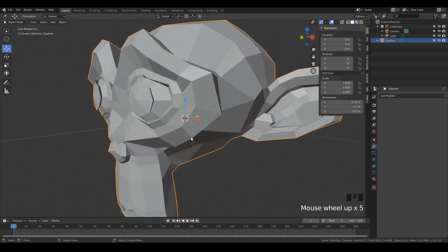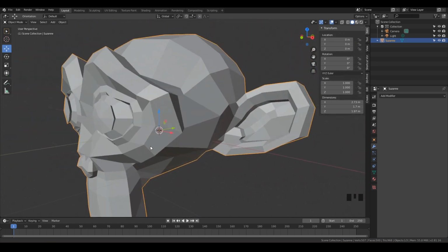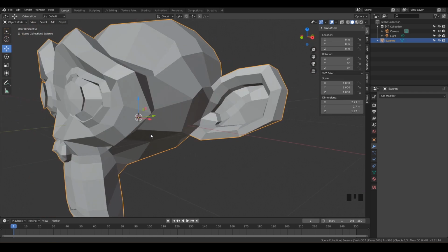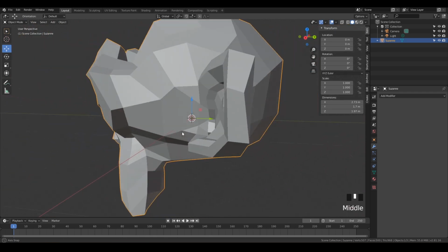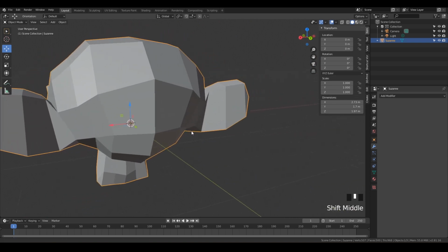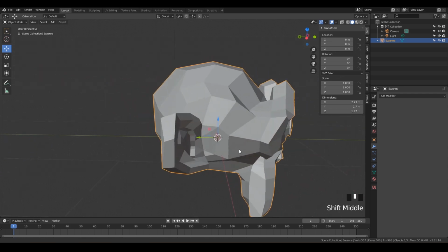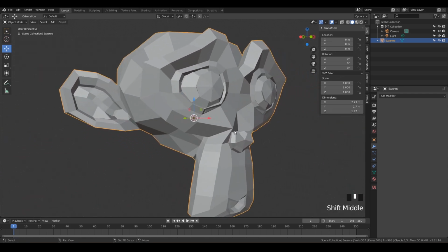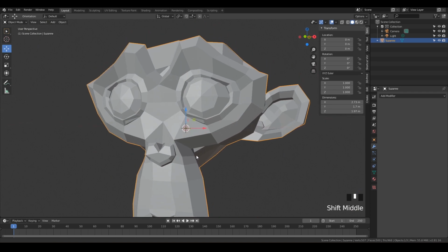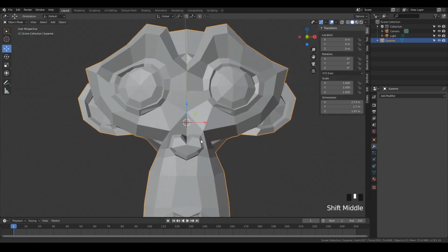And then the third way you can move is the pan. So to do that, just hold Shift on your keyboard and then push in your middle mouse wheel, and that will kind of grab your view. You're not orbiting around, you're just sliding it left and right. So sometimes you may click the middle mouse wheel, hold Shift and pan, and then orbit, and then pan, and then orbit, then pan, then zoom. So just try and use all those together. That's the goal of this lesson, is really just get comfortable moving and panning and zooming.